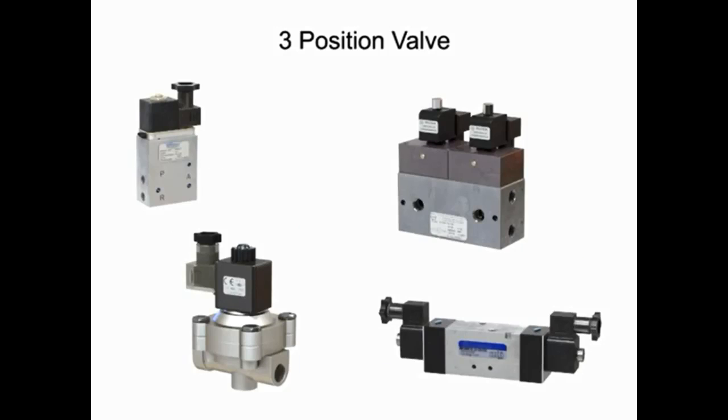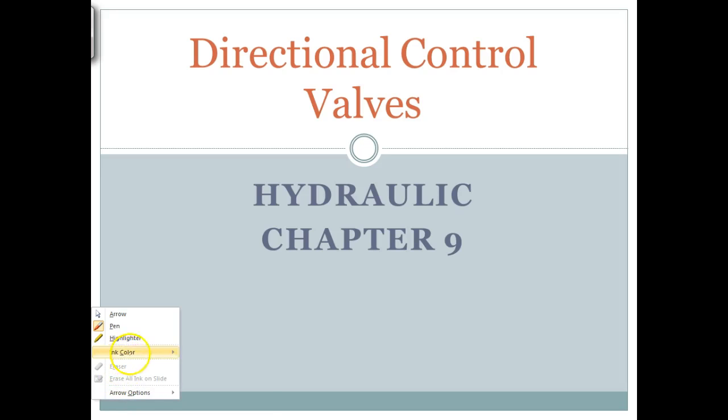Solenoid valves are used in both hydraulic fluid and air systems to control direction on cylinders, deceleration or speed control, and pump unloading or pressure control. The physical appearance of each component will vary greatly depending on brand, size, and type, so care should be taken to reference the appropriate manufacturer's guidance when choosing a solenoid valve.